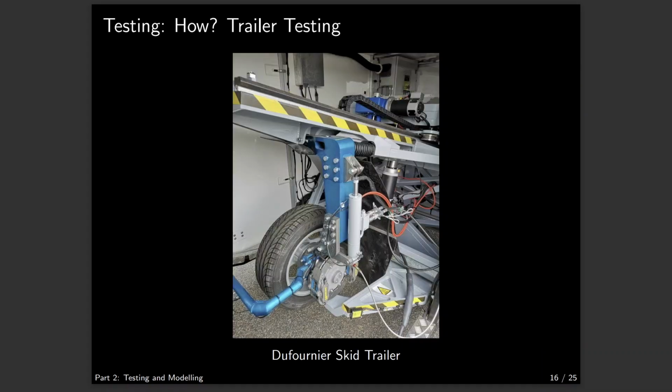So if the belts are inaccurate, why not test on the actual road? Well, that's the main advantage of the trailer testing. There's several papers about people who have even DIY built these themselves. What we're looking at is a similar device to the belt tester, but now instead of a drum with a belt, we are physically towing this entire device behind a truck and putting the tire on the actual ground. There's even versions of these with water cannons that can measure how much water the tread pattern displaces. A potential disadvantage with these is getting those really big steer angles without upsetting the stability of the trailer and causing a hazard. Additionally, controllability and repeatability begin to degrade as road surfaces vary in roughness and temperatures.